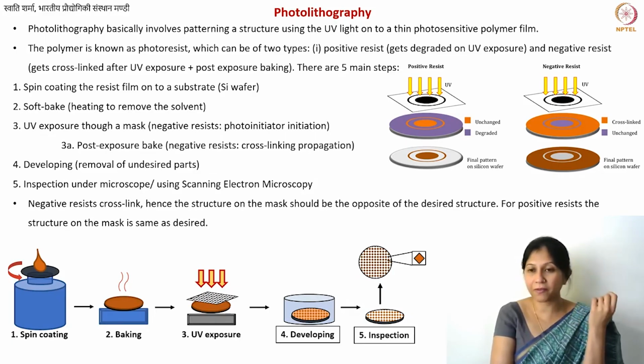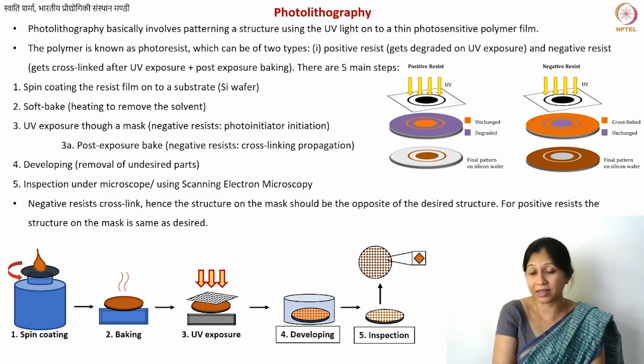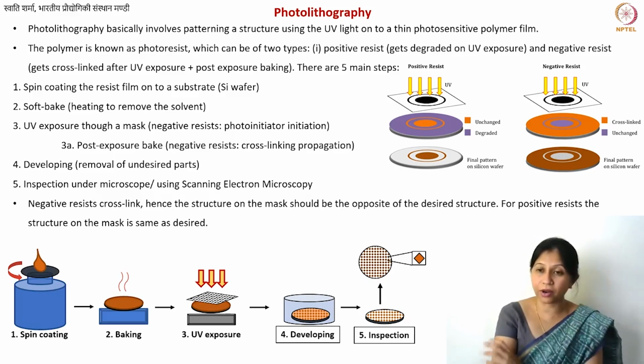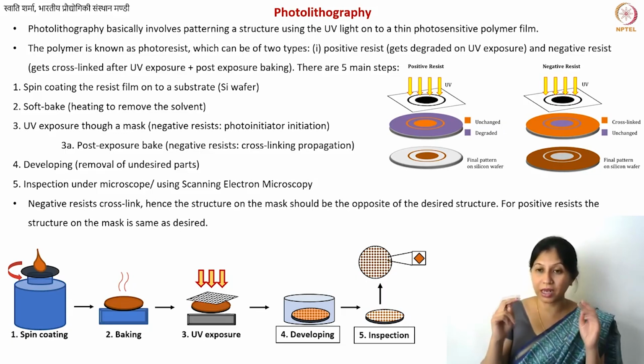In the case of silicon wafer, silicon-based technology is very widely available, because it is used in the IC industry. So the thin film technology for silicon wafers, these spin coating techniques, and all these machines are easily commercially available. And also the best thing about silicon, for its popularity in the IC industry, is the fact that you can grow films on top of it, silicon oxide films or silicon nitride films.